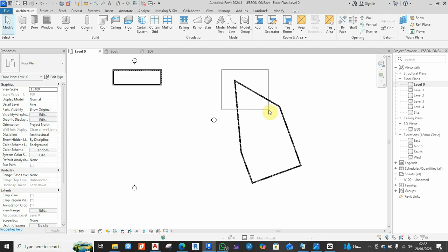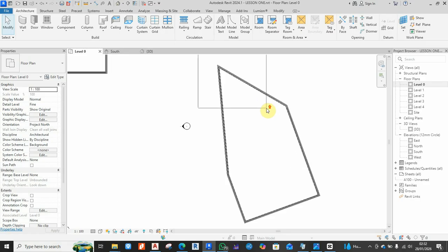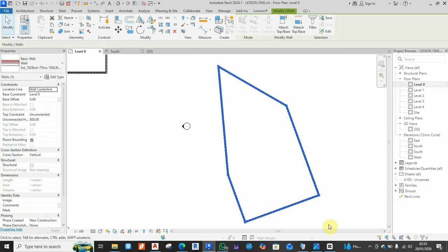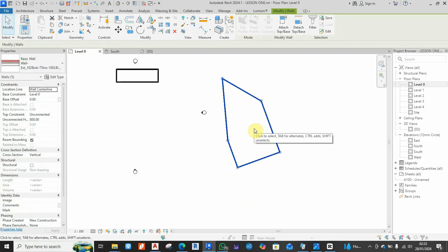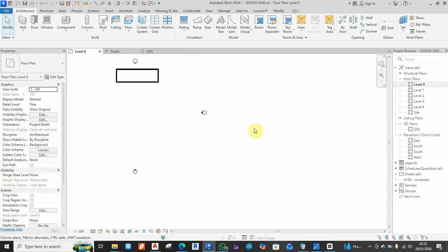As you can see, as soon as my selection box covers the first wall, that wall becomes highlighted. I keep dragging it down. It covers the second wall on the left, it's highlighted. I keep dragging it down. The guy on the right, you see, until if that is fine, I release to select, and then I can click delete, to delete. So that's the first method of selection.